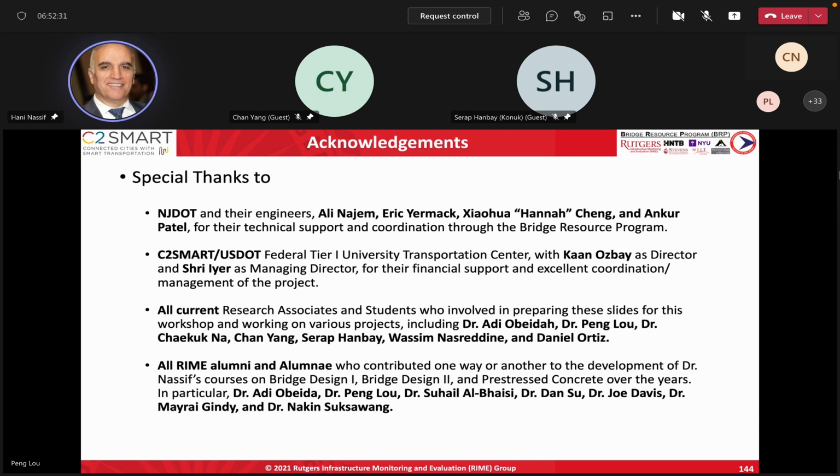When you have a combination of both, how do you calculate the stress at ultimate? And how do you find the capacity of both? We developed some equations, and we are validating them. We are also using FRP tendons. Daniel is now doing work with FRP tendons, but also with ultra high performance concrete. We were able to mix them and build them in the lab. I think that so far he has about 4 or 5 of them done.